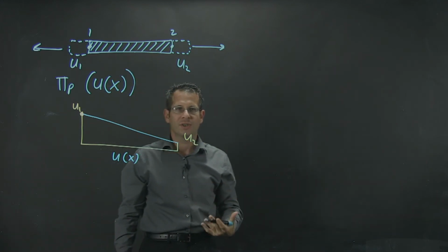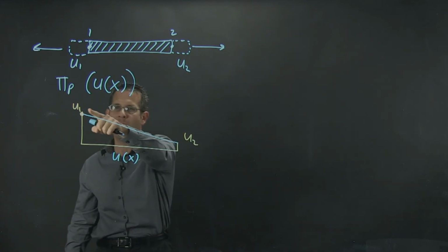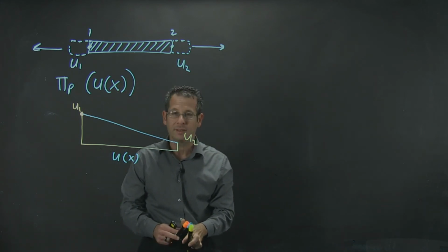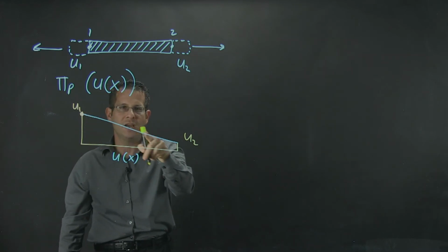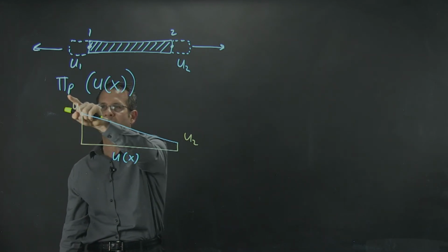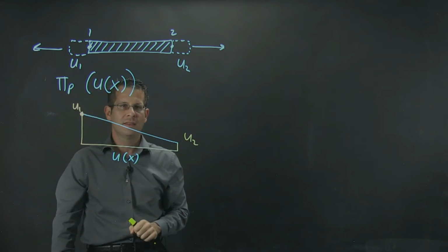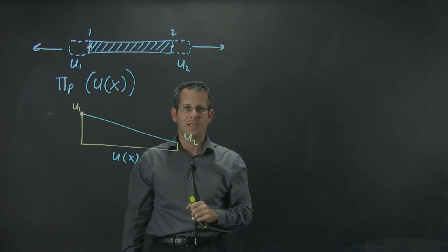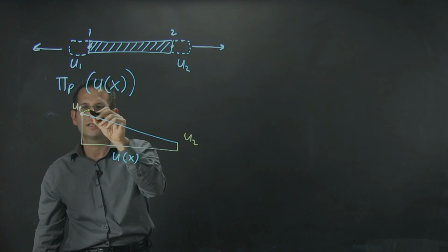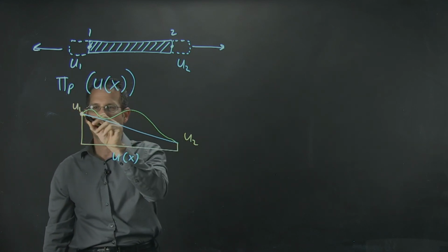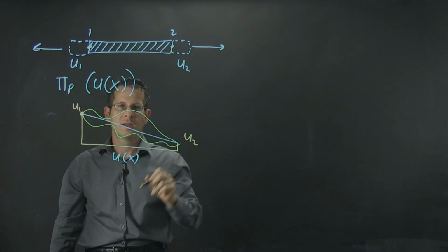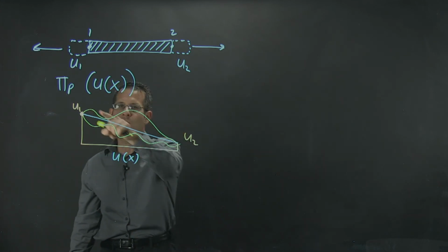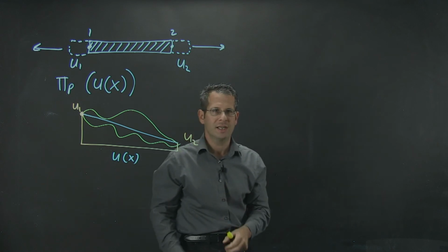But it also turned out to be a straight line because of all the possible displacements and all the possible displacement functions I could have, this is the only function which minimizes the function of my total potential energy in the system. There are other possible displacement functions, and these functions are perfectly valid for the displacement, but they don't minimize my total potential energy in the system.